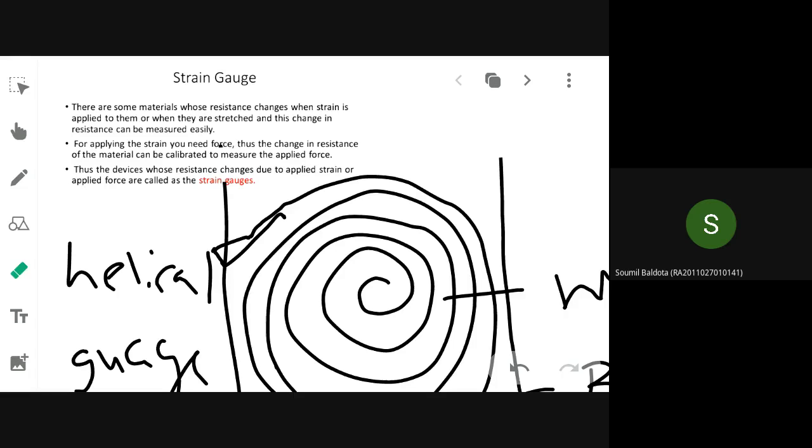What are the particular types of transducer we discussed yesterday? LVDT and capacitive transducer we discussed yesterday. So capacitive transducer works on the effect of capacitance. It will be having one fixed plate, a static plate, and a diaphragm. Depending upon the applied force or pressure, the diaphragm moves. So it will act like a capacitor plate which will be converting the force into an equivalent signal, that is the capacitance effect. The distance between the two plates is changed, so the area is changed, so it will automatically change the capacitance. So this is how a capacitive transducer works, which we discussed yesterday.